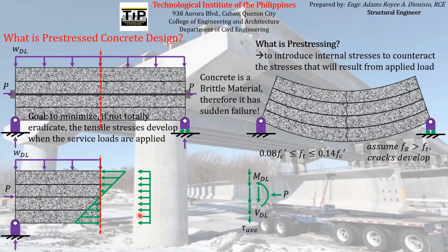So we can assume that the stresses that this axial force produces on this cross-sectional area is uniform, just like this one. So let's just call the magnitude of that axial stress that came from this axial force, let's just call that f sub P. So stress that came from the axial force P. And again, since this force points towards this concrete beam, obviously it produces compressive stresses. So that's why I indicated here negative to indicate that these stresses are compressive stresses.